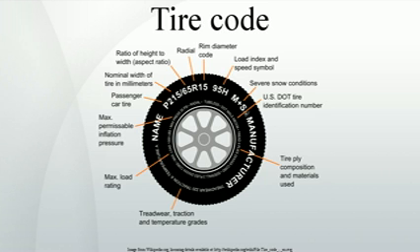The code gives a direct calculation of the theoretical diameter of the tire. For a size shown as T/A/W use: 2 × T × A / 100 + W × 25.4 for a result in millimeters, or T × A / 1270 + W for a result in inches. Take the common example used above: 2 × 195 × 55 / 100 + (16 × 25.4) = 621 mm, or (195 × 55 / 1270) + 16 = 24.44 inches.